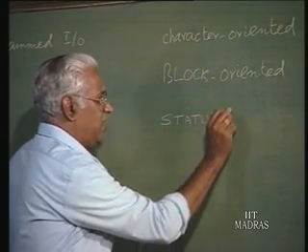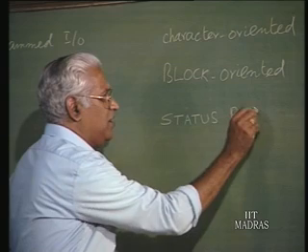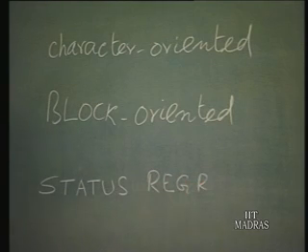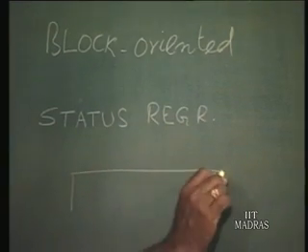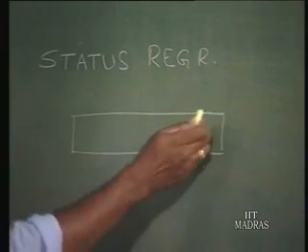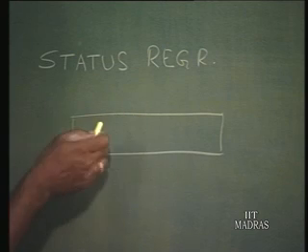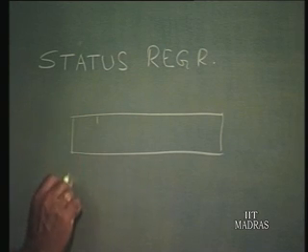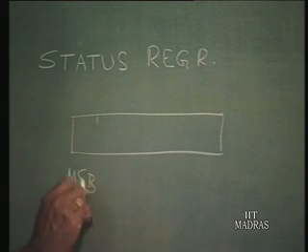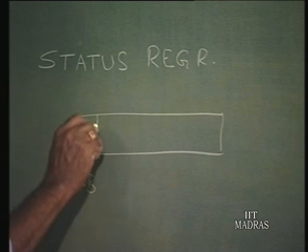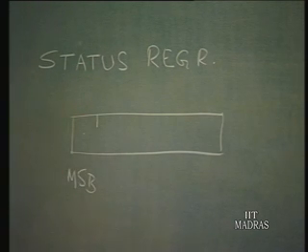Recall I also said the status register, for instance the very first bit of whatever be the size, let us assume a byte. So, let us say the MSB, that is the most significant bit. Now, this particular bit, depending on whether it is 0 or 1, is going to indicate whether it is ready or not ready. Okay.